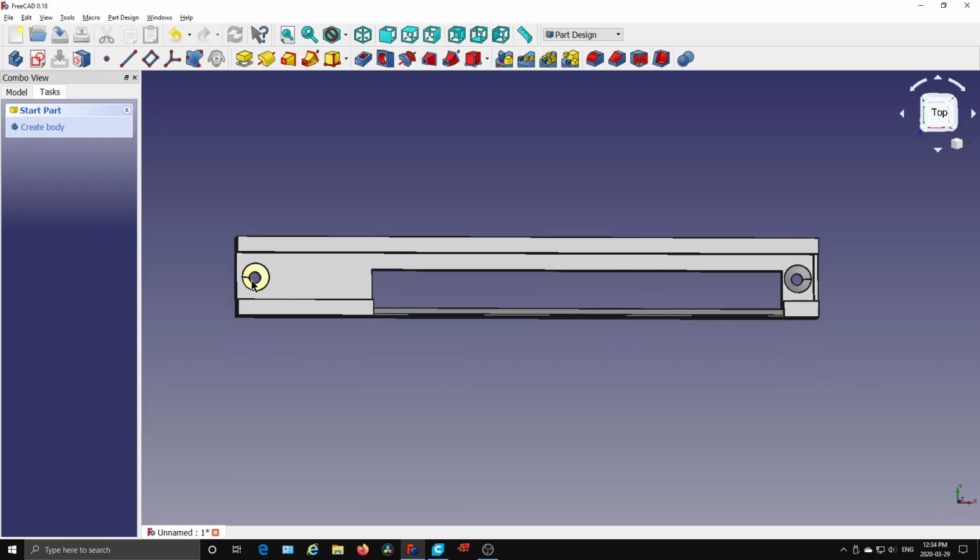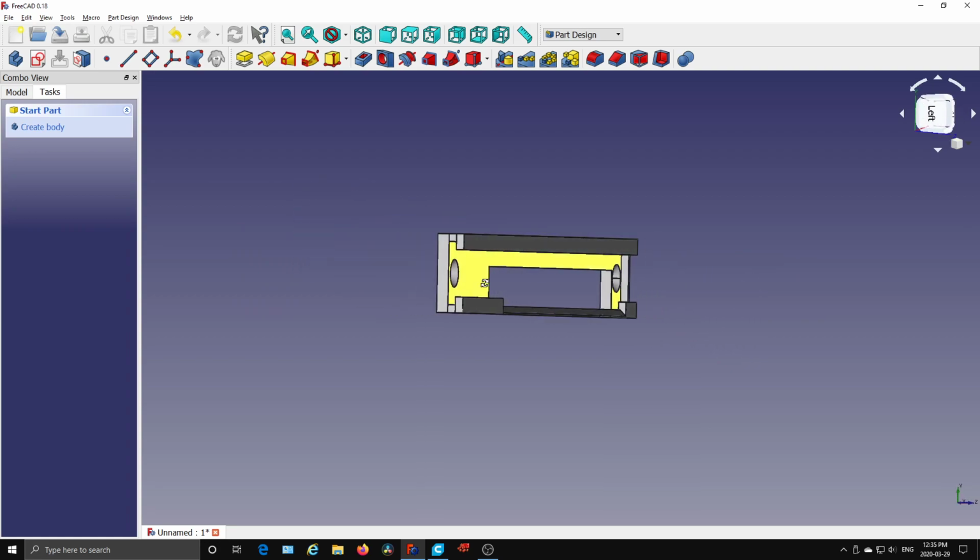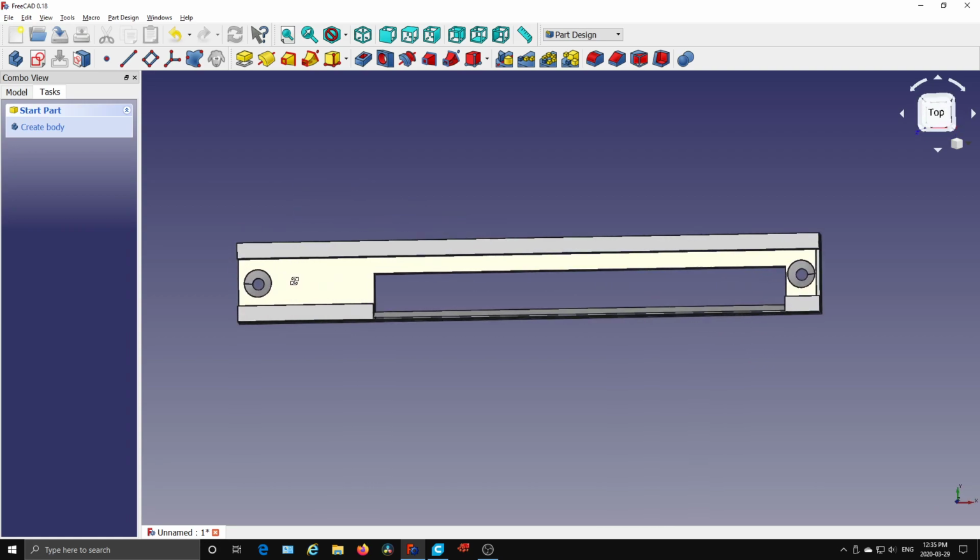And these tapers should be deep enough so that the top of the wood screw will sit below the surface of this pad. You don't want the screws sticking up above because then the slide, when you put it in the end, will not slide easily past the screws. You want the screws to be slightly below the surface of this area. So that's pretty much it for the sliding portion of it.